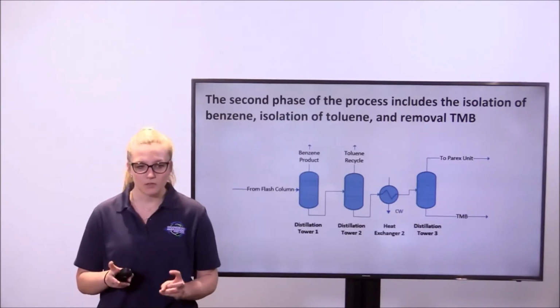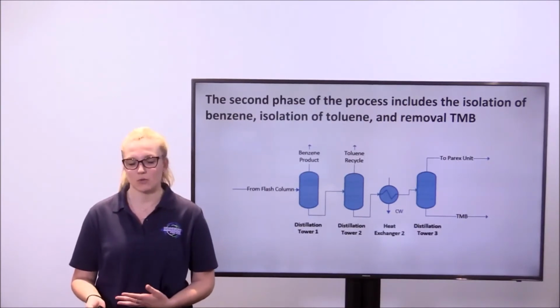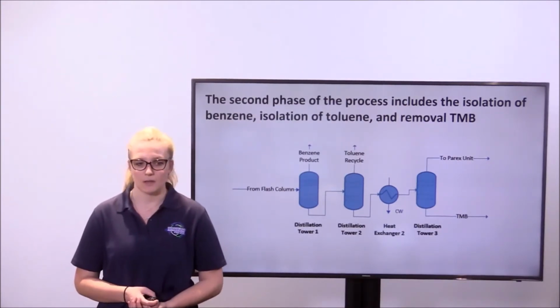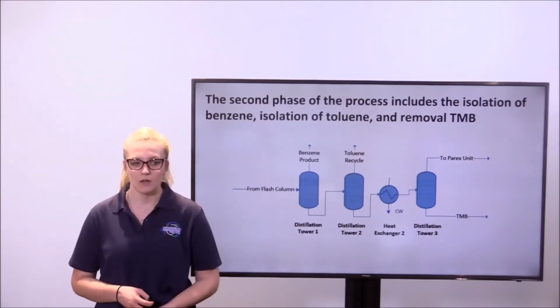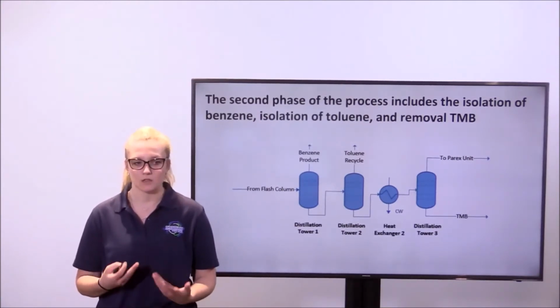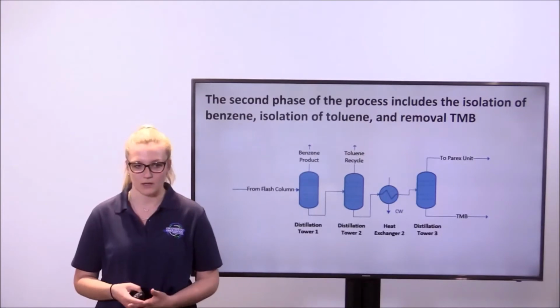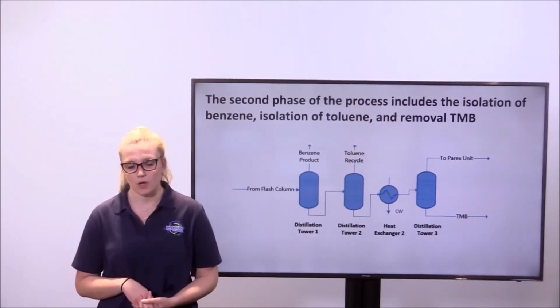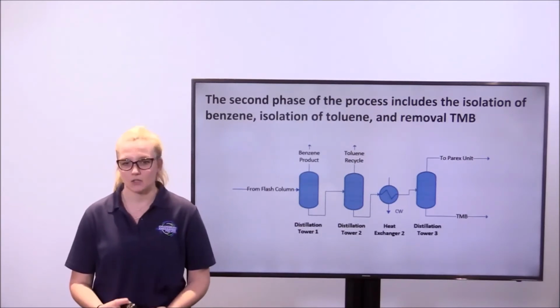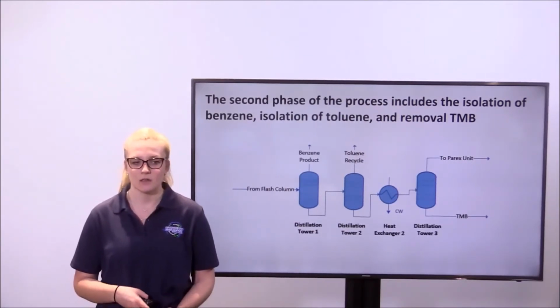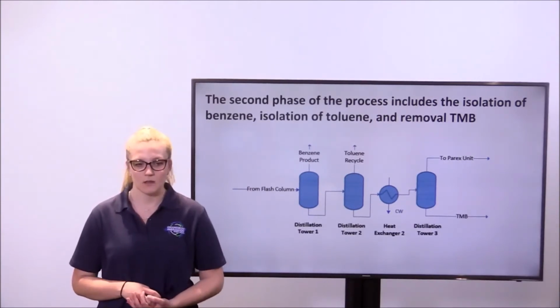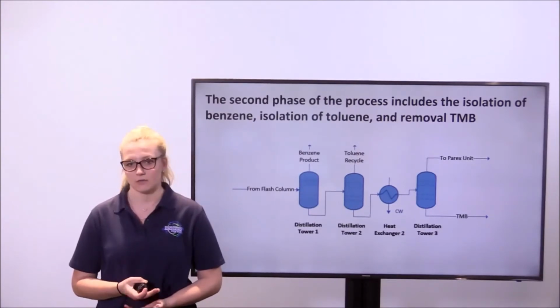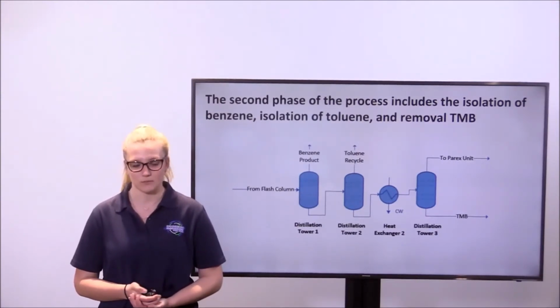The purified bottom streams from Tower 2 will then be sent to a third tower to remove the TMB. So after the third tower, the stream is almost our mixed xylene products. So although a series of towers do lead to a higher capital cost for our plant, in this case it is justified to have 3 towers due to their different purification goals and their unique design aspects. They deliver different products for our plant, and they deliver different recycle streams as well, which can be used.